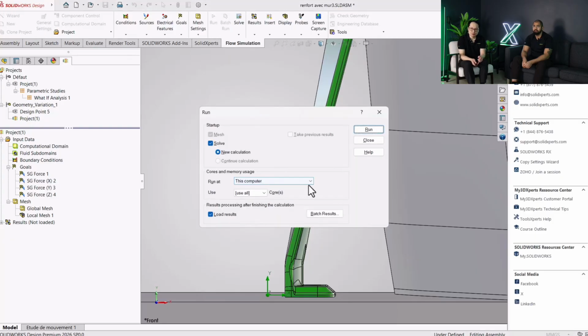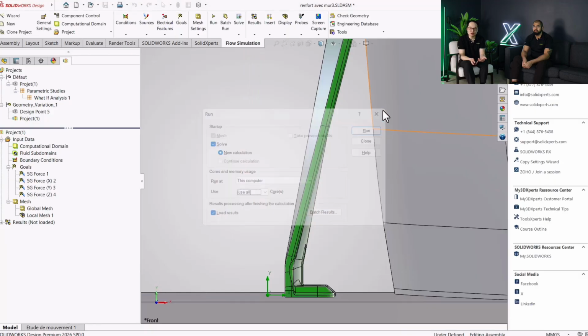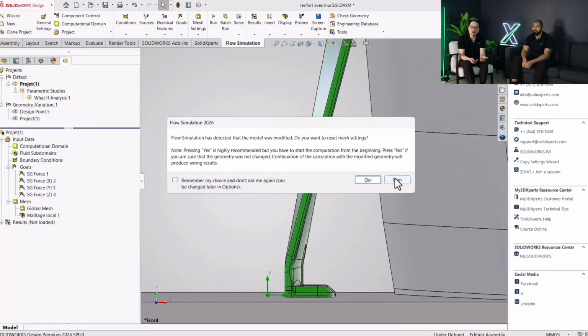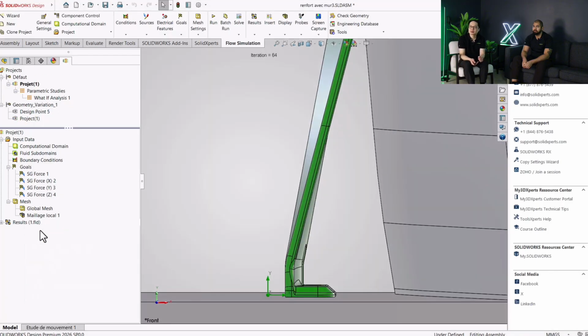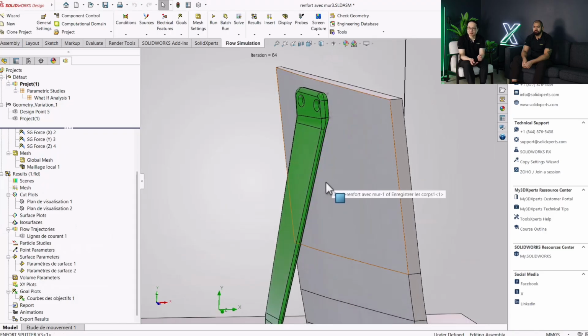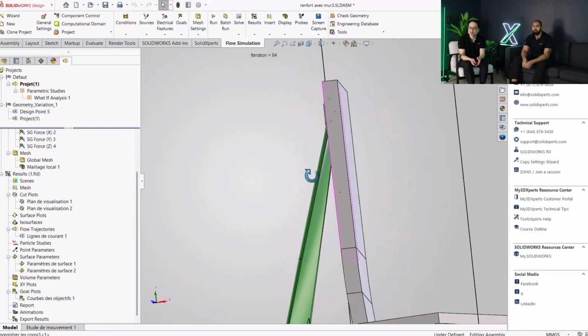So there you go. The first thing we should do is verify that the analysis was set up correctly. We often say garbage in, garbage out when it comes to these analyses. So we make sure the flow is moving correctly, using a trajectory plot, as we can see here.